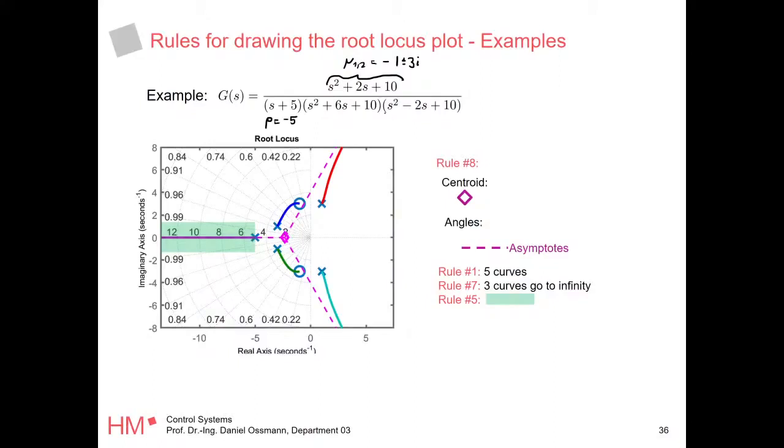This one is actually pretty easy to solve. This is actually just mirrored. If this term is negative, it has the same roots as this polynomial, just the damping is negative, right? So you basically switch over to the right half plane. This one has poles, let's call them 4 and 5. They must be +1 plus minus 3i. I mean, you can do the calculation, but this is definitely the same polynomial, just with a sign change. A sign change here means we mirrored the damping to be negative, so this is an unstable pole pair.